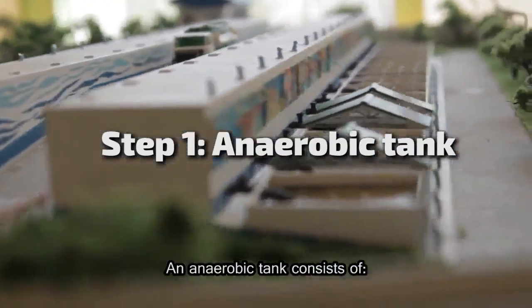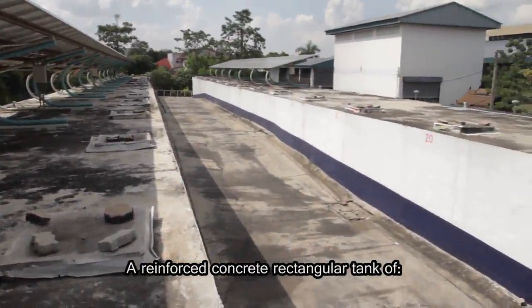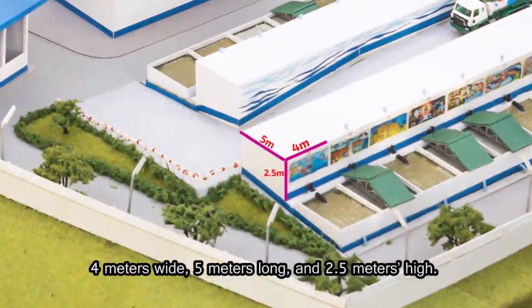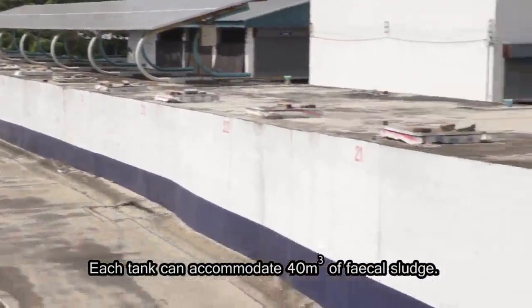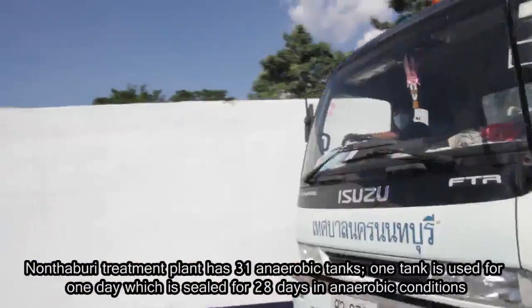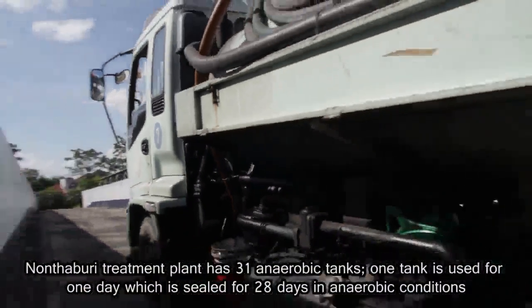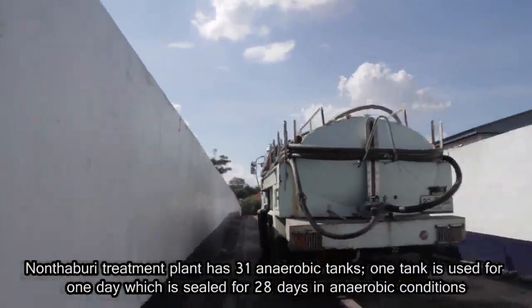An anaerobic tank consists of a reinforced concrete rectangular tank of 4 meters wide, 5 meters long, and 2.5 meters high. Each tank can accommodate 40 cubic meters of fecal sludge. Nonthaburi treatment plant has 31 anaerobic tanks. One tank is used for 1 day, which is sealed for 28 days in anaerobic conditions.